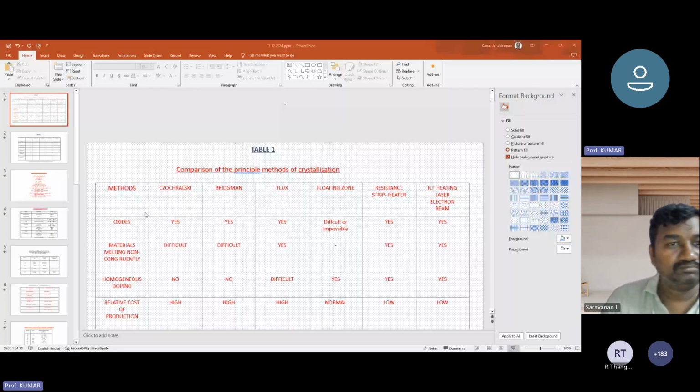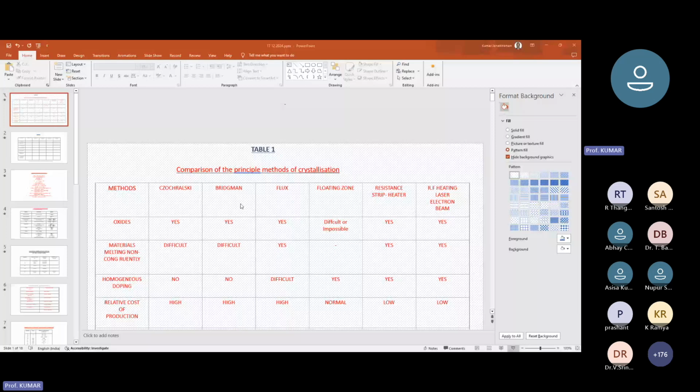And we can have the carrier density in this range, like 10 to the power 17. And typically, you get mobilities which vary with respect to the carrier density. If the carrier density is relatively high, generally the mobility is low, because sigma is equal to n e mu, and therefore the mobility will be less if the carrier density is relatively high.